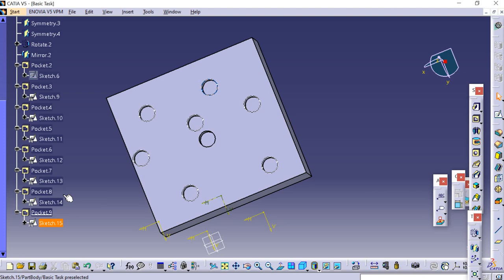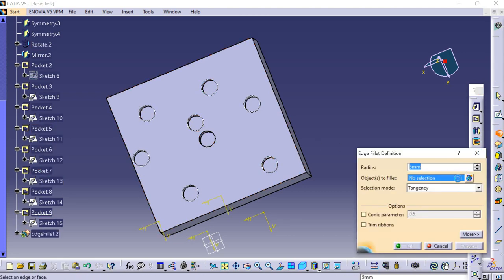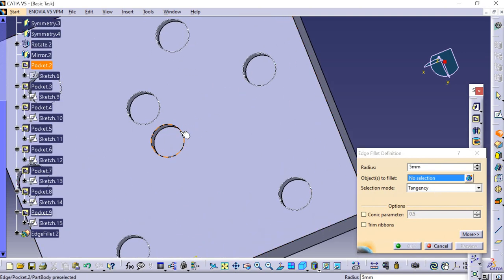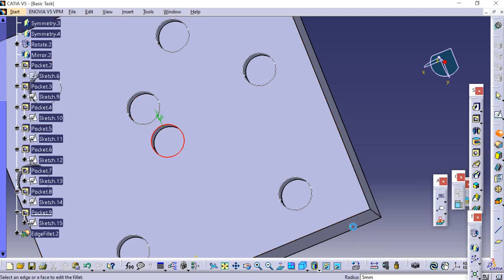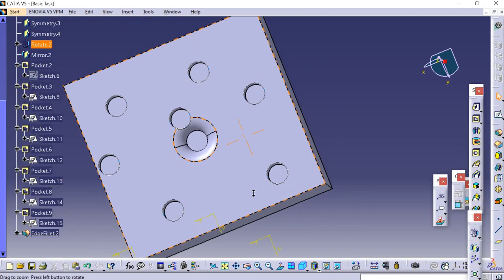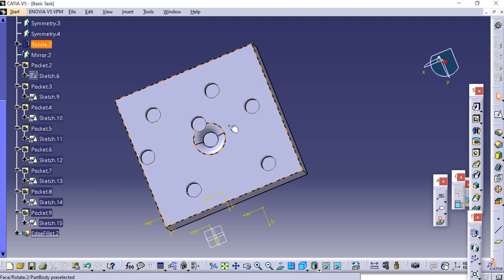During our designs, we may decide to perform specific operations on a certain number of instances. So if we want to perform an operation here, we want to fillet it, then we can do it separately, like that. Or else everything will get filleted at the same time. So we use exploding patterns.